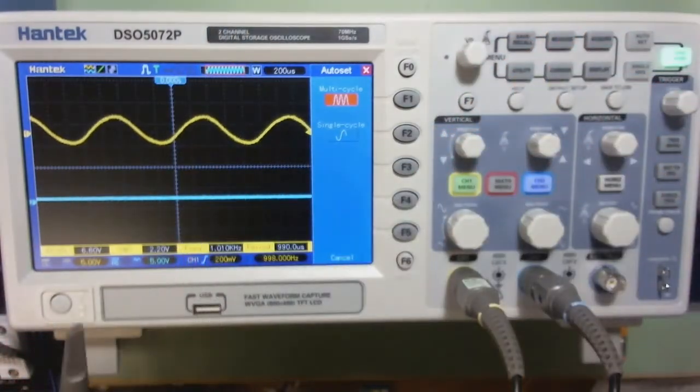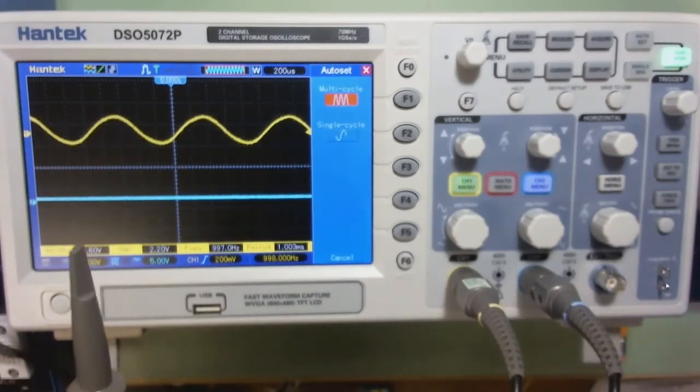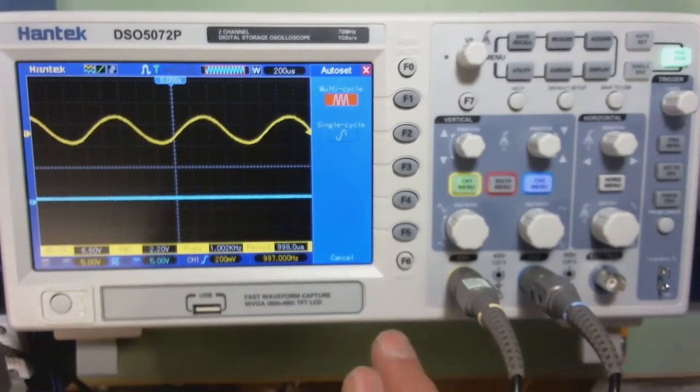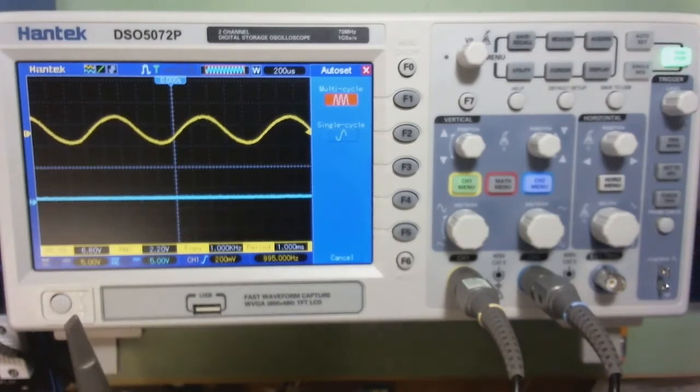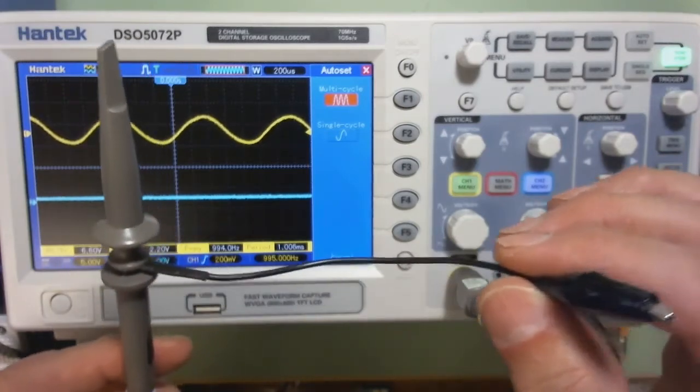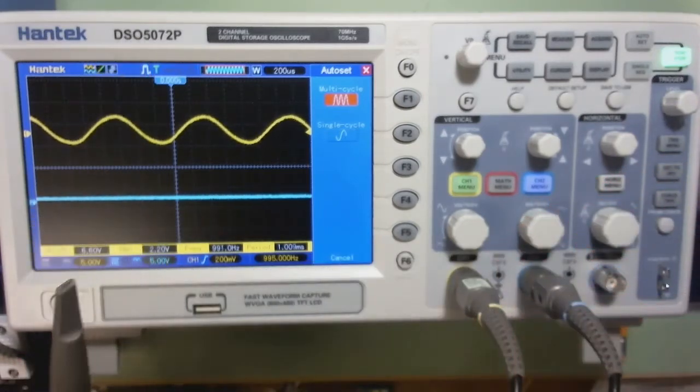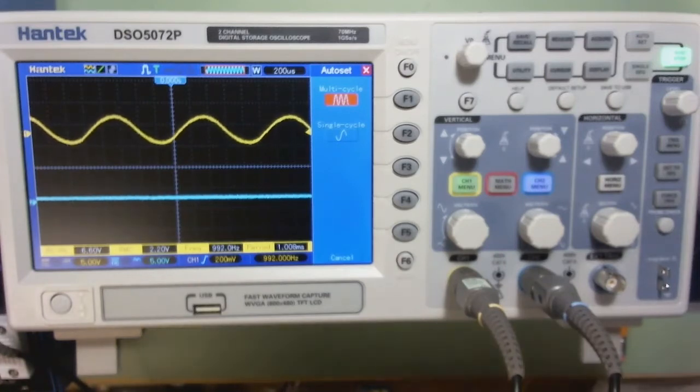And that's something to think about when you're measuring a circuit, particularly if you're trying to use this on measuring some live AC. You have to be really careful. Is your circuit ground the same as this oscilloscope reference? If it is not, you may not want to hook up this ground wire. We're not going to have to worry about that in the upcoming labs, but if you start to do a lot of oscilloscope work, that's something you may want to think about. The really cheap and dirty trick is to not ground your oscilloscope, but that has some safety problems.